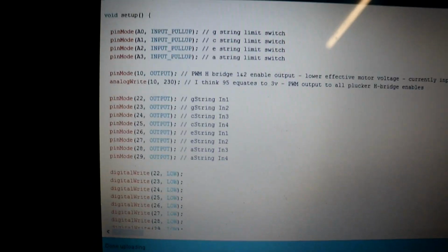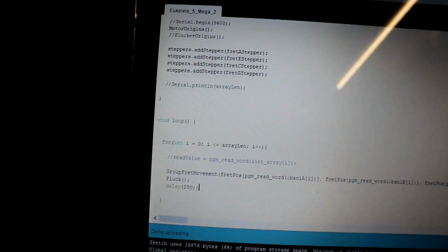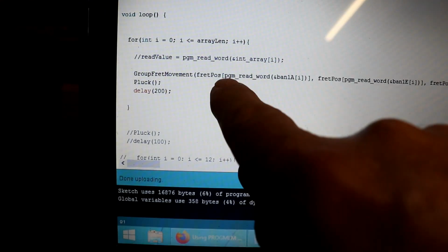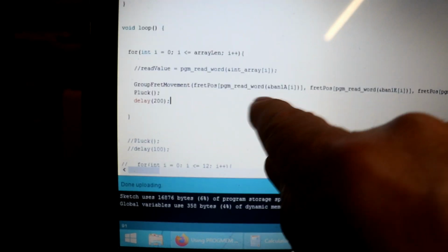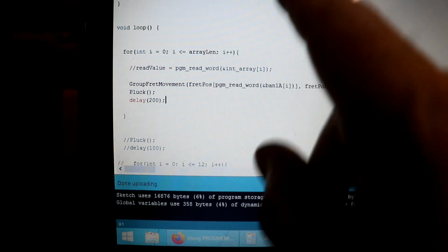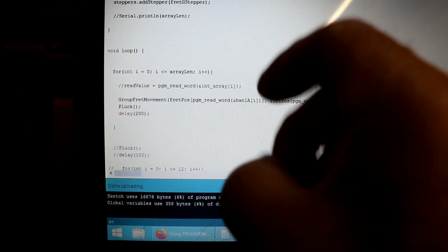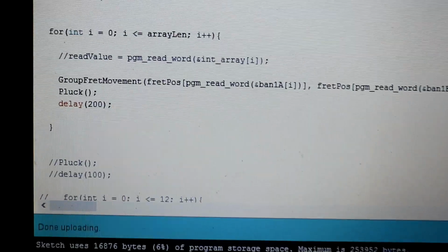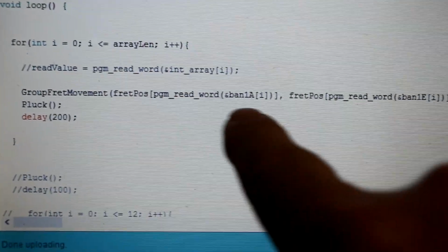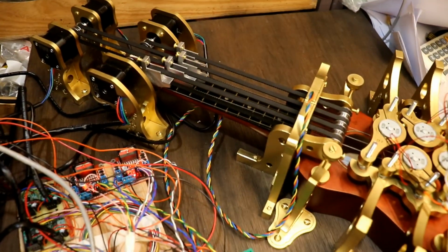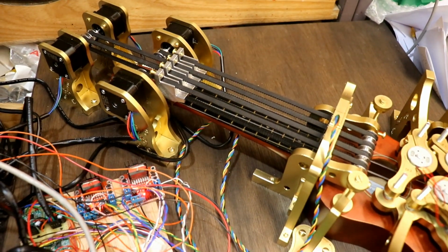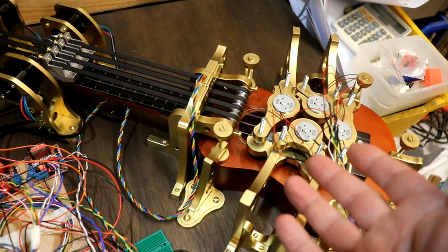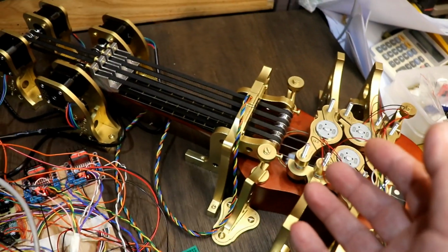If you do save it in PROGMEM, to read it you have a little pgm_read_word and an ampersand reference thing in front of it. When I wrote the scribulator, it was so complicated because I was reading all sorts of stuff I'd encoded myself. It was a nightmare, but it's as simple as that. And rather disturbingly, it is actually reading... I don't know what that's all about.